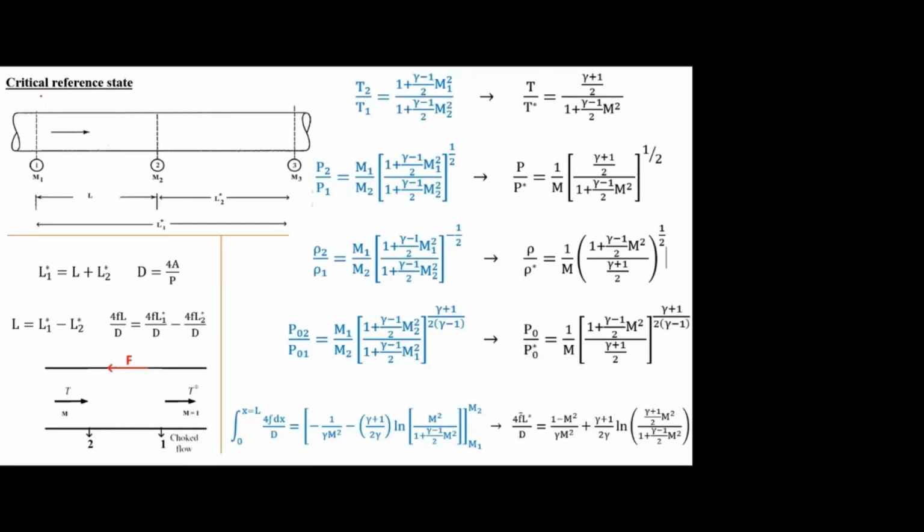So for example, I will take the first problem. They have given Mach number 0.3. It is accelerated to 0.475 for the 30-meter length. Okay, this is the original duct. Now imagine I am just extending this duct imaginarily. I am adding another 20 meter so that I can convert this 0.475 to 1. Okay, now this 0.475 will reach sonic if I add this 20 m.